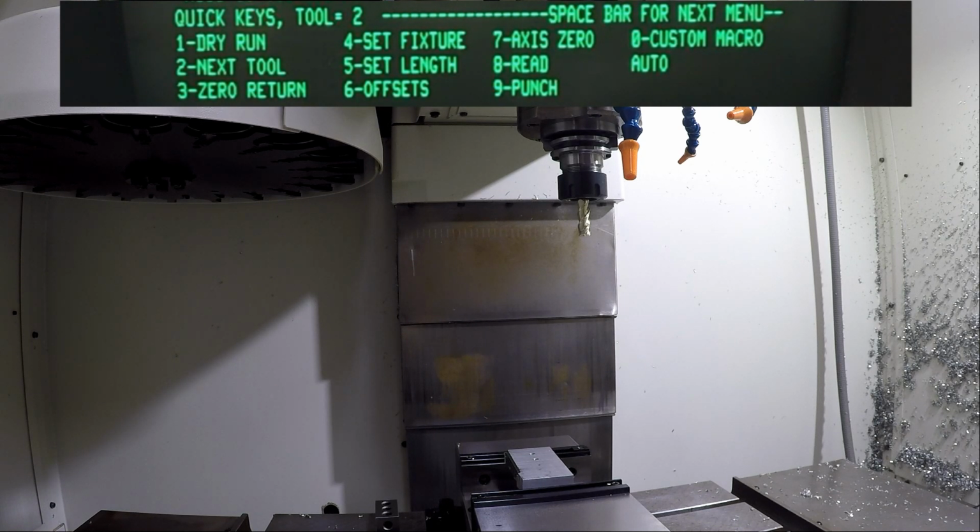And that position you can set wherever you want, depending on where the Z is. If it's, I think, above or below the cold start Z, it'll move. If it's below, I think it moves the Z up first, up away, and then it moves the X and the Y. And if it's below or above, it might move the Z down. I can't remember exactly, but I know depending on where the spindle is at the point that you say go back to 0, it'll move one way or the other.